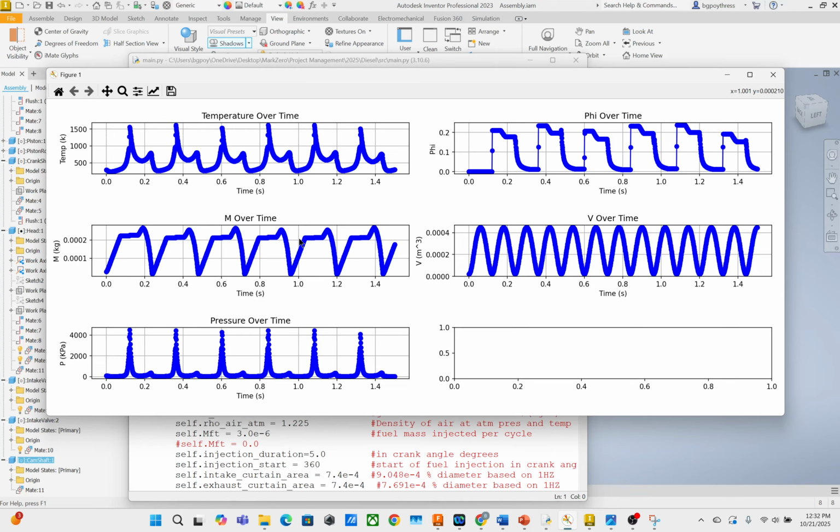Most engines of today, 2025, are direct injection engines, meaning that there is an injector here that injects directly into the cylinder, into a bowl in the piston. This bowl is there so that the fuel can swirl with the air that's in this gap and properly mix.